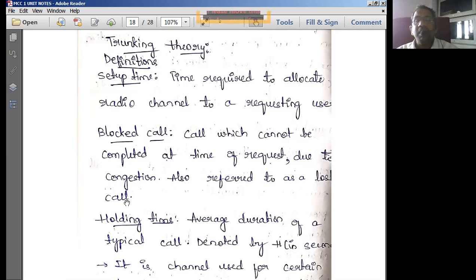In this, there is one drawback, as we explained earlier. What is the drawback that we can see here? The drawback is that even though the two mobile units are adjacent to each other, the call has to go through all this process, so it takes a lot of time. In this process, if the channel is not available, it simply says that the call cannot be reached now. That is one of the drawbacks we can encounter in this kind of simple direct setup mechanism.